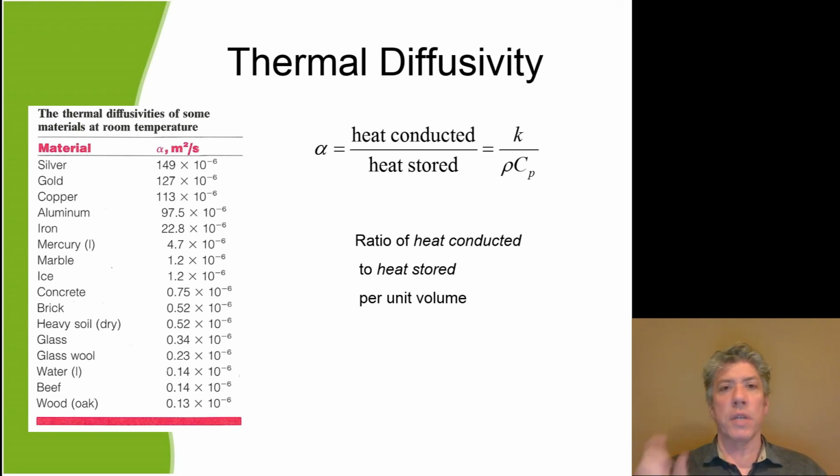And so the engineers were saying, no, we need fins on the back. And what the engineers were thinking was, we need to reach steady state where all of the waste thermal energy is pulled away from the LED and then pushed out to the air. But that ratio of heat conducted, so through, versus heat stored, really is my point of this story.